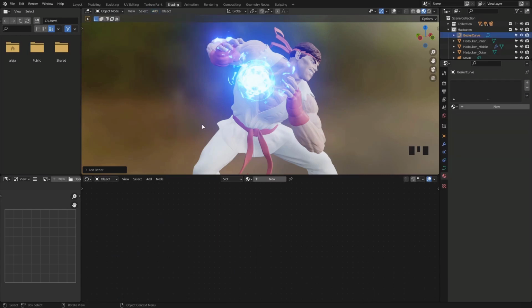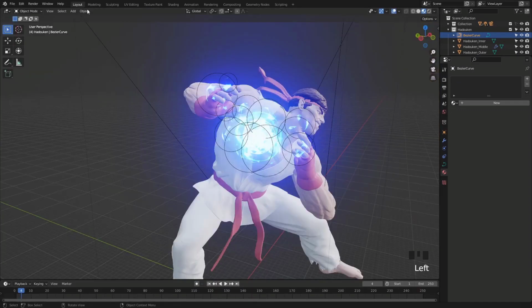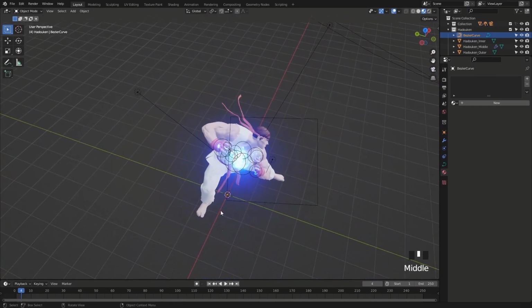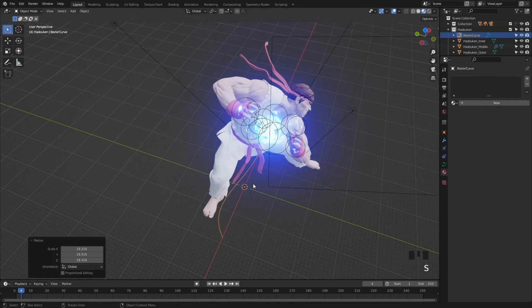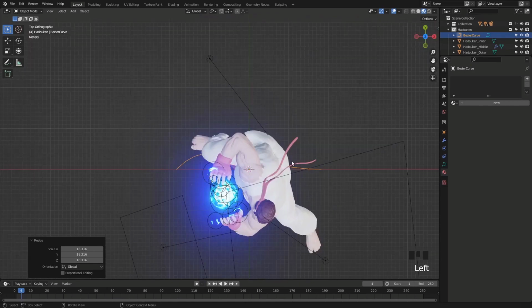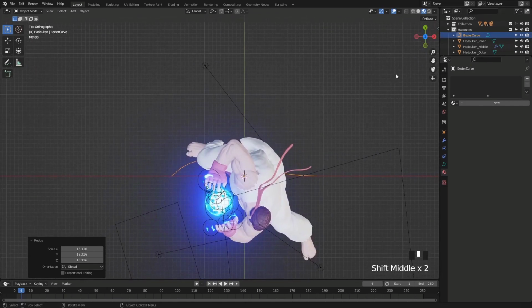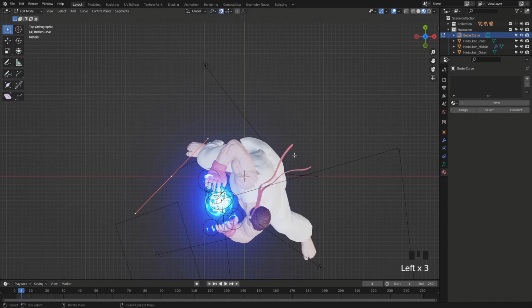There we are. And with this Bezier, you can't really see it, so let's go out of the shading editor and come over to the regular workflow, sorry. And let's just press S to scale, and there it is. So now you can see it. What I'm going to do is come over here to the top-down view. I'm going to move this in edit mode. I'm going to turn on the snapping to increments with absolute grid snap. What this will do is snap into place to the grid that I have here.